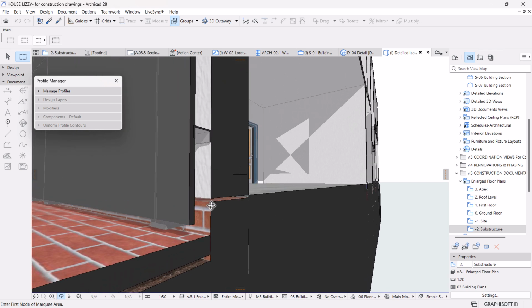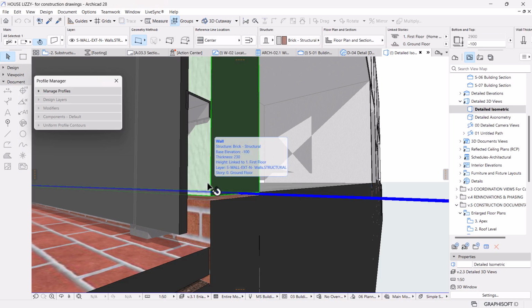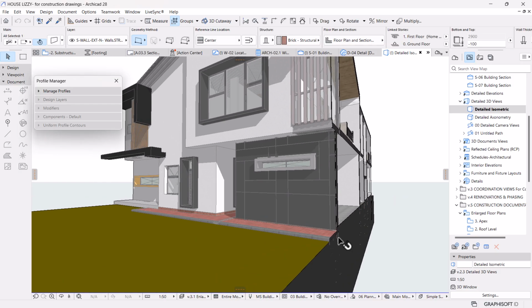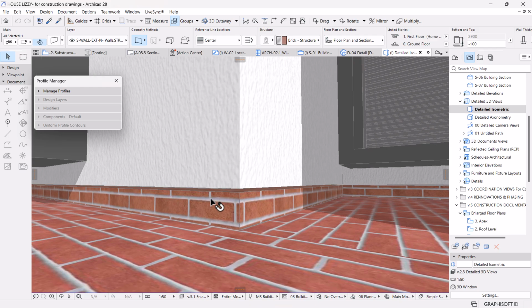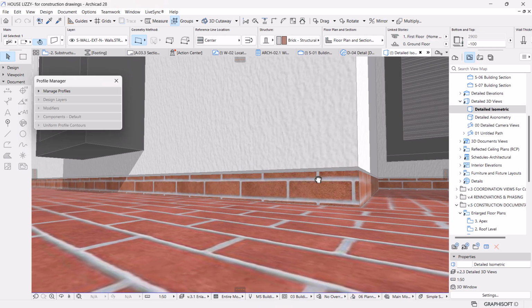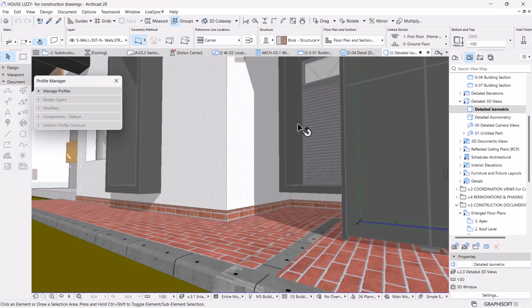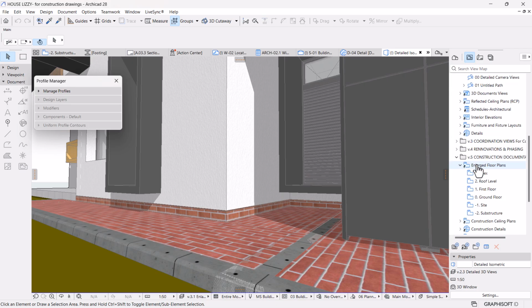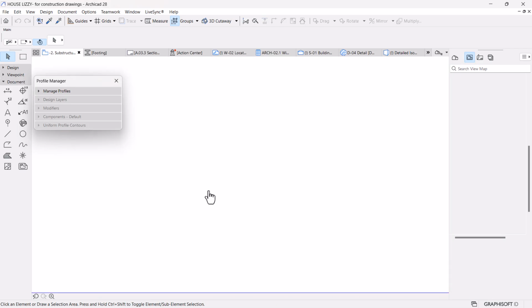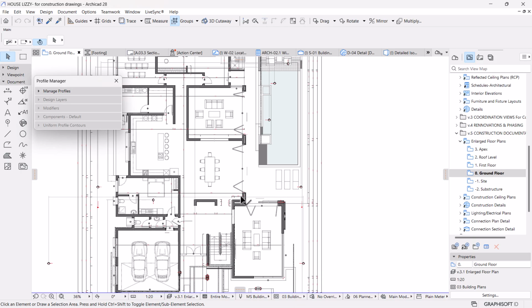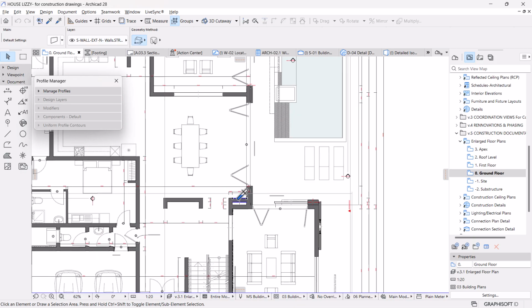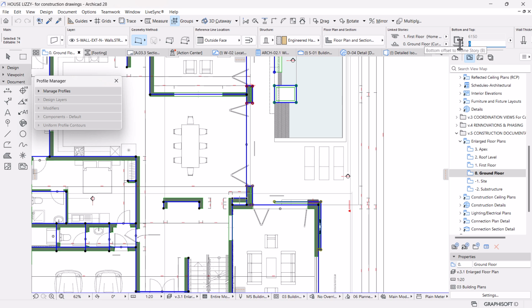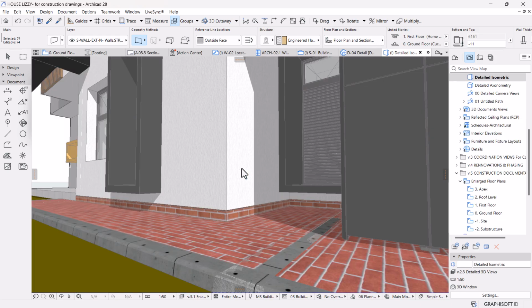You see there's a big gap that we can easily fix by just dropping our, let me see down here, even here is also occurring. Maybe I can just fix it by going to the floor plans. Where are we? Going to the ground, sorry, and select all the walls, drop them down by 11. I'm going to select all of this, then say minus 11. This should automatically fix the gap.